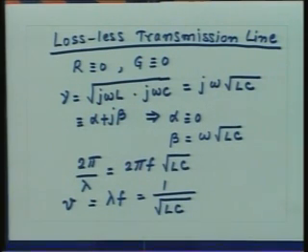If I consider the two conductors of the transmission line and vary the separation between them, the mutual inductance is going to vary. So, the net inductance of the line is going to vary, but at the same time, since the separation between the conductors is varying, the capacitance also is going to vary. So, when I try to vary the inductance, the capacitance varies and vice versa. Precisely that is what we are saying: the inductance and capacitance per unit length on a transmission line are not independent quantities. The product of them is constant, because that is related to the velocity of propagation of the wave on the transmission line.